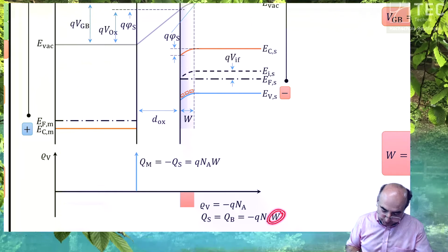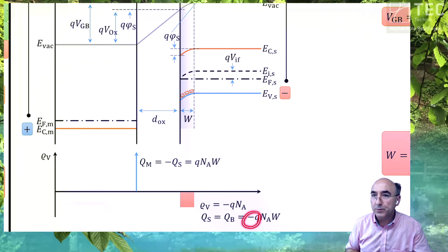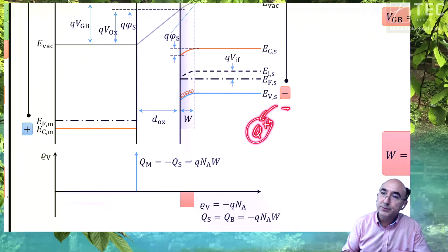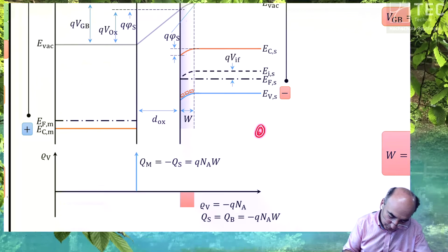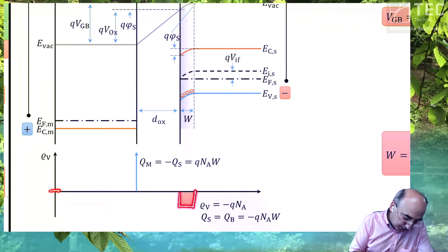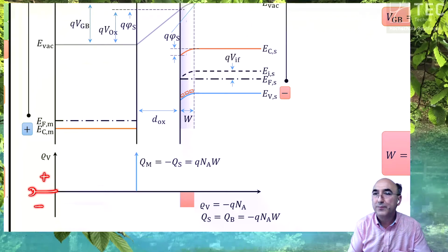You calculate it by the space charge extension, by the doping concentration, and by the value of the charges. So if you have a p-type semiconductor, you have boron, and boron accepts one electron and is one times charged negatively. Therefore, this minus sign. Therefore, the box at the lower side here is negative, here is positive, and here is 0. Okay.